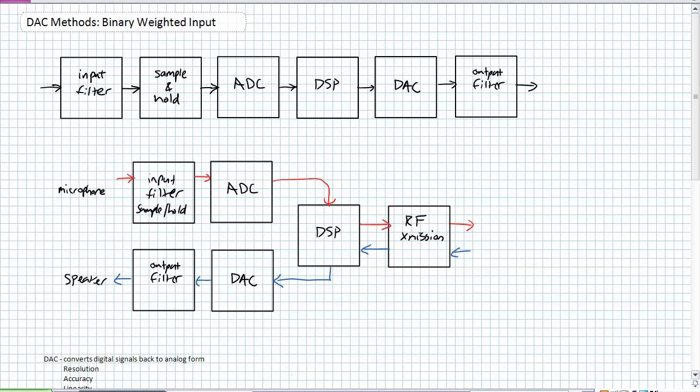The DSP, once it's got that digital information, what's it doing with it? Now, this is the point. It is digital information. You could potentially error detect and error correct. You could perhaps encrypt this transmission, and at which point it's going to hand that digital information off to the RF transmission portion. In addition to all that, doing something with the data, the DSP is also handling the protocol of cellular communication.